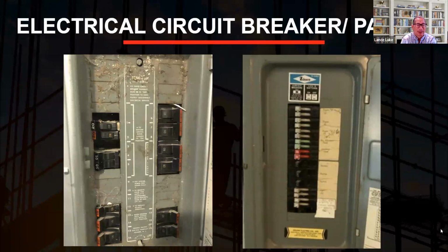So the first brand name is FPE, which stands for Federal Pacific Electric, and it's the specific Stab-Lok, STABLOK. And that's been known to fail. And when I say fail, I mean that when you have an overload, the breaker does not trip. What is a circuit breaker for? The circuit breaker is supposed to break the circuit. So if there's an overload or short, that circuit breaker will trip and cut the power off. Now, what happens when you have an overload or a short circuit and the breaker doesn't trip?